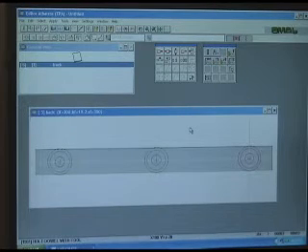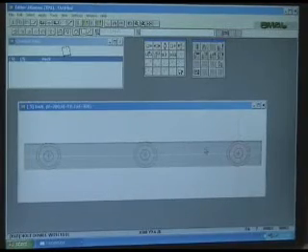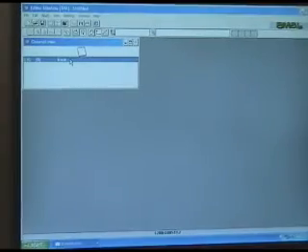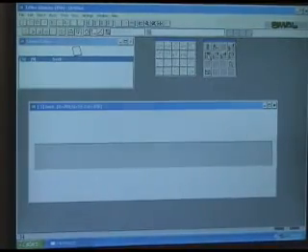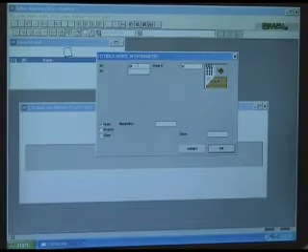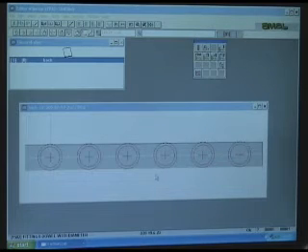So if you're downloading from a cabinet design package, then the machine can easily receive parametric programming as well as absolute programming. We can specify a beginning and ending point and fill the panel with holes. Let's just say 20 millimeters is the beginning point, and length minus 20 millimeters is the ending point. Step is 32, and we will fill the panel with drill and dowel. So this is put as many as possible in the panel.